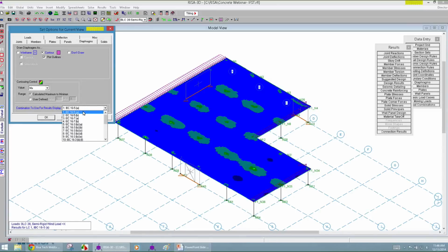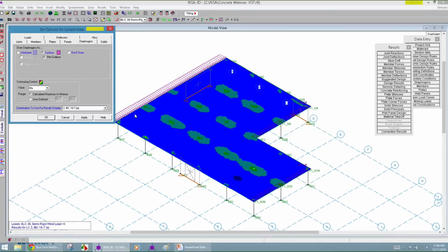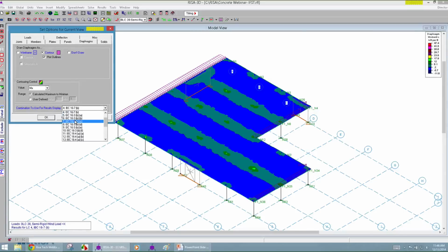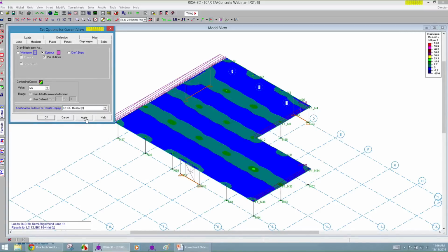So you've got a lot of different load combinations to look through. You can see that in the display, you just toggle the below there to see which different load combinations are causing. Maybe what you might want to do is find a high deflection. That might be something that would be an indicator of the worst case for us, and see how the loads are being distributed through the forces, through the actual diaphragm.